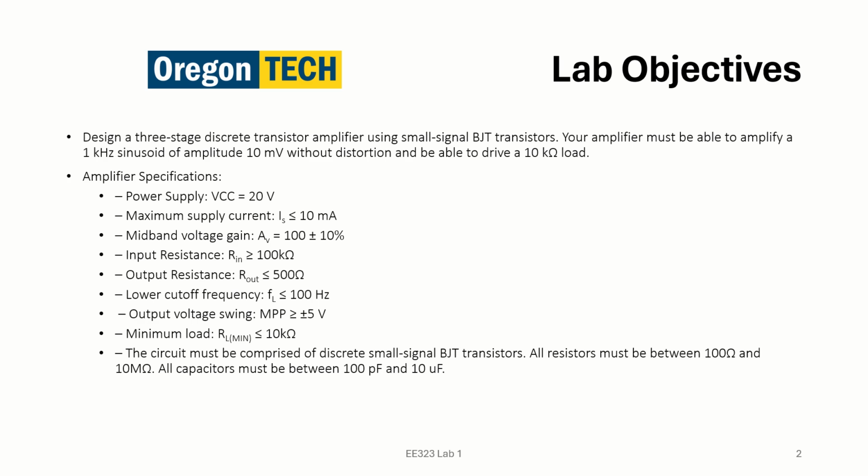An amplitude of 10 millivolts is 10 millivolts peak. And 10 millivolts peak is also 20 millivolts peak to peak. So when you're in the lab using the lab equipment, or if you have a signal generator at home, it's important to know the difference between amplitude or 10 millivolts peak and 20 millivolts peak to peak.